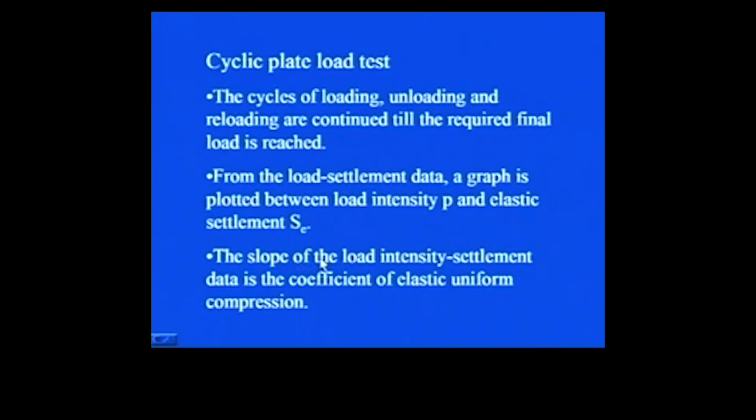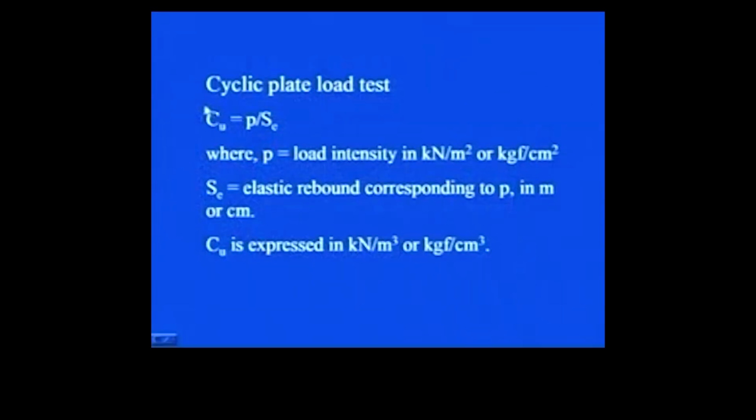So from the load settlement data, directly you will be getting this load intensity P versus elastic settlement, and the slope of this particular curve will give you the coefficient of elastic uniform compression. So I hope that now you understood how you can get the coefficient of elastic uniform compression using cyclic plate load test data.